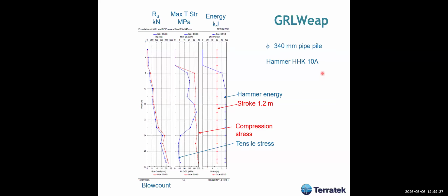But what I do today, I prefer to rely on experience. Usually I can do this kind of analysis, but I prefer to rely on experience and then to do a pile dynamic test in the beginning, on the first piles, in order to check the stresses, driving stresses, etc., and pile capacity.